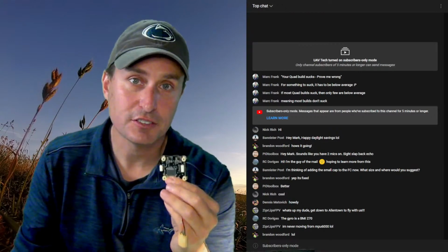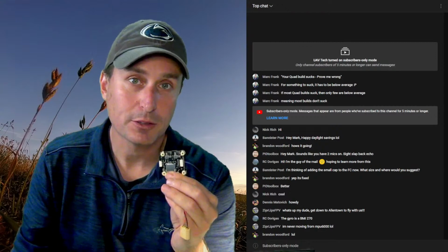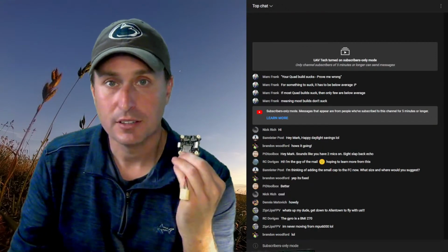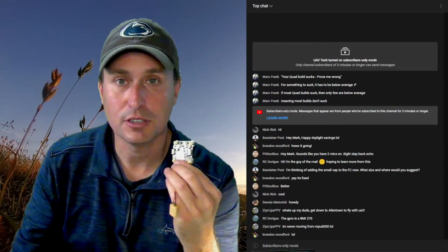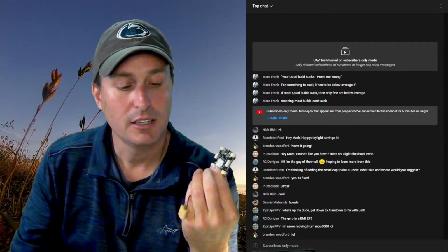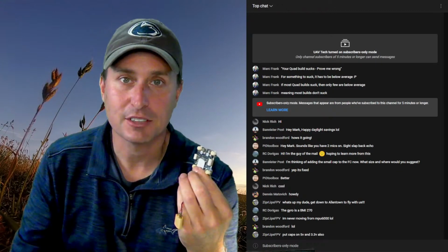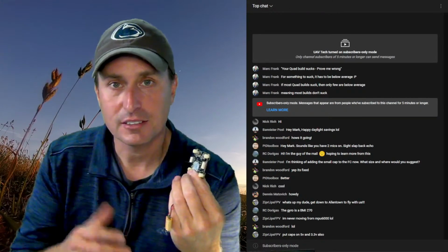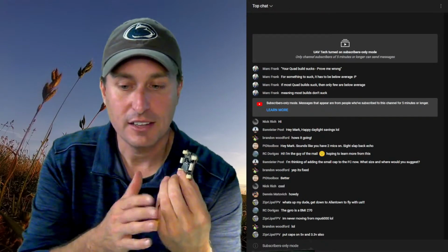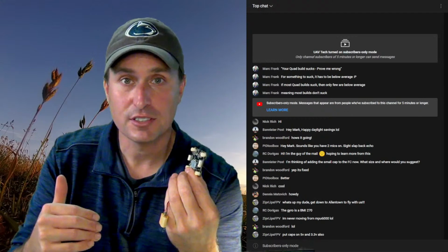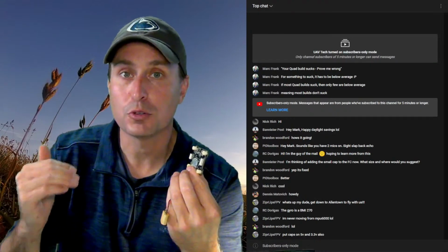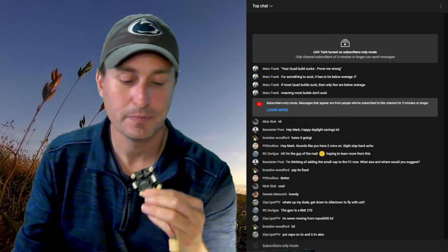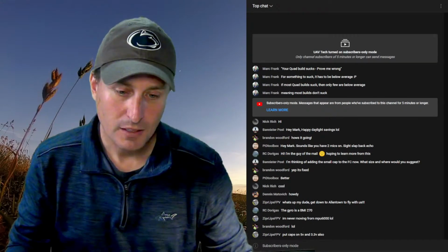A lot of cinelifters do that right off the bat. They power their camera and all their sensitive electronics with separate power. Those are huge, 2 kilogram plus rigs, so it makes a lot more sense, especially when you have expensive cameras on board. It's not for racing quads and things like that. It's more just a test. If you see a noticeable difference by doing that, then you know for sure it's an electrical issue. So you're not guessing, is it the gyro, is it electrical? So that's one thing you can do.